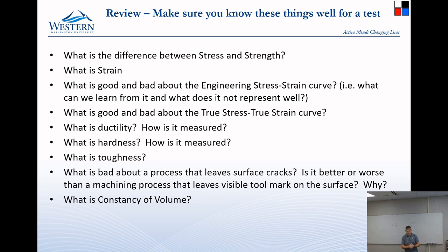They used it. They launched a bunch of planes that had parts that had been made on wire EDM, and they failed. They failed because of this surface finish. And so all of a sudden they said, nope, we're never using wire EDM again. Just not gonna do it. It's not worth the risk. Turns out you can do processes to remove that surface finish because it's only on the surface, and then you can use the parts. But it's taken a long time for that industry to come back to being willing to even consider electrodischarge machining because of that.